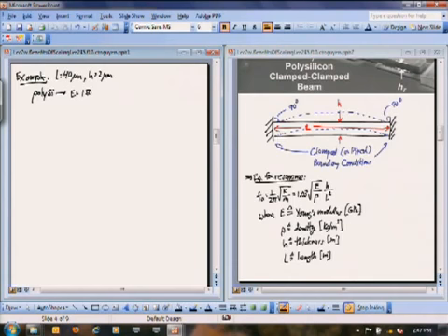The density of polysilicon, 2,300 kilograms per meter cubed. And therefore, if you just plug all of this into this expression, take my 1.03 times 150 giga, and so you're encountering my shorthand notations here. When I want to say giga, which is 10 to the 9th, I'll write a capital G, divided by 2,300.